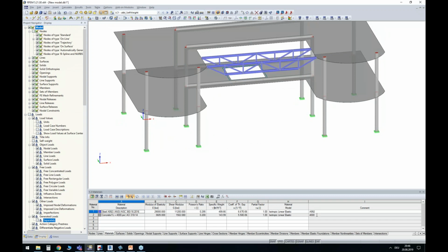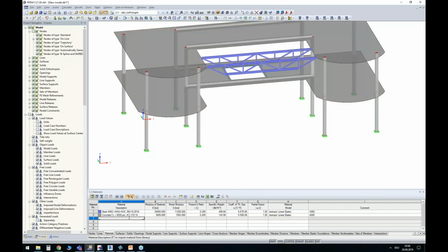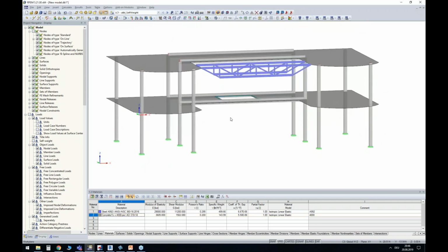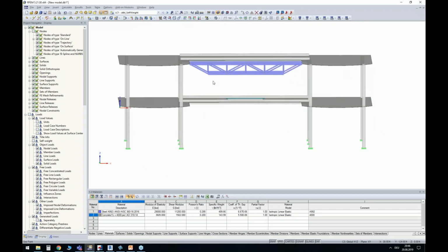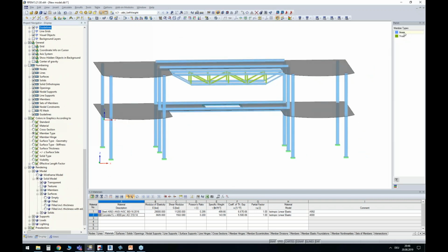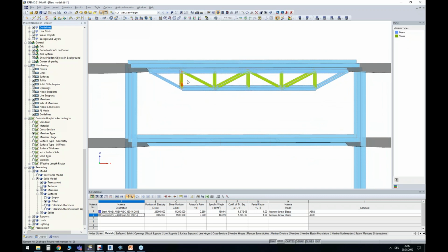You can see in Revit, the concrete that I'm using here, the concrete with 4,000 PSI, is only the name of that in Tekla is just 4,000. So if I would have imported only the pure name without the conversion tables, I wouldn't have gotten any value. Yeah, so the conversion tables again help me to convert it correctly into a material from my library. And what else? Yeah, we also have these truss members that I defined in Tekla. So you can render that complete structure according to the type of the member. Then you get a small panel on the right-hand side. You can see that blue is a beam member, green is a truss member. So that was the option that I defined in Tekla and also Revit before.